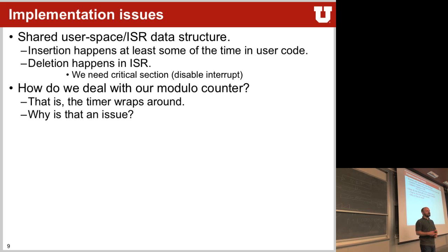Software bits. Yes. Remember, your timer will probably tell you when it overflows. It will generate an interrupt when it overflows. So you could just read that interrupt and then have a software bit counter that counts how often we overflowed. That way, you can actually extend your timers in software fairly easily.